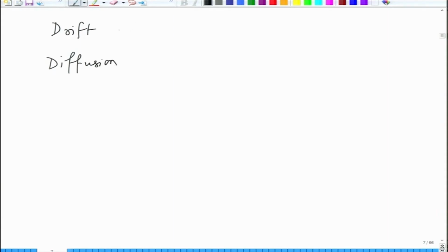Now this is the conductivity. Okay. The current that you obtain is J is equal to sigma E. Okay. This is pertaining to the drift part, where carriers move under the influence of electric field. But you may also have a current because of motion of charges. The charges do not necessarily move only because of electric field. They can also move if you have a concentration gradient.